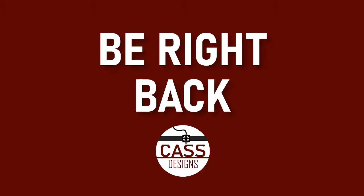All right, so you click this, and since this is such a sharp turn, I'm going to click the check mark. It's going to finish that spline, and we're going to start a new one right at the end of it. So still just outlining. Doesn't have to be perfect, like I said, probably 20 times. Now we're going to go here, and then okay. And then for these flat parts, we're going to go back to normal lines.